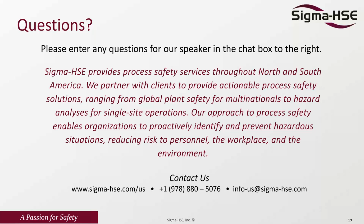With incident investigations, we want to learn why things happen, keeping in mind that all incident investigation root causes are a management system failure. If you fix the management system failure, the event or incident will be unlikely to happen again. Also, both of these, the management of change and incident investigations, will need to be incorporated into the 5-year revalidation.